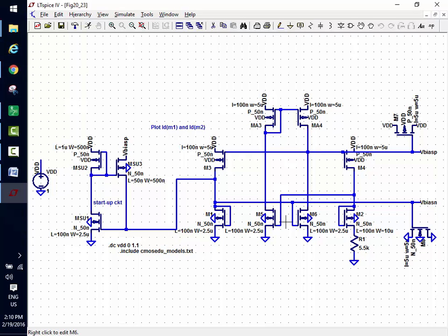Okay? So what are these 4 transistors then? They're the diff amp we just went over. So all I've done, I've removed the gate drain connected transistor here. I've gate drain connected these to try to set them to the same value. I've added this amplifier because I want this voltage and this voltage to be the same. So let's see how the performance is.